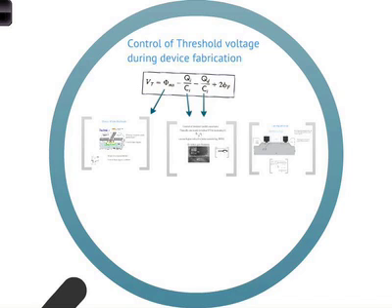You don't want that to be too high. If you make that too high, that means in your integrated circuit, you need to provide a power supply that can go to a high voltage that you don't really want to do, because it's expensive, it's hard to do, all that stuff. So you want to keep it relatively low. But you don't want to make it too low. If your threshold voltage is too low, then any little noise in the circuit can turn on the transistor, and that's very bad.